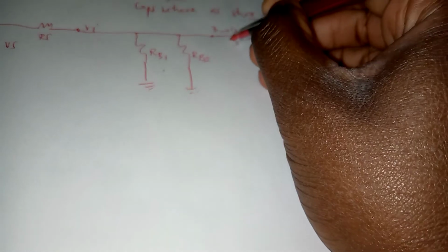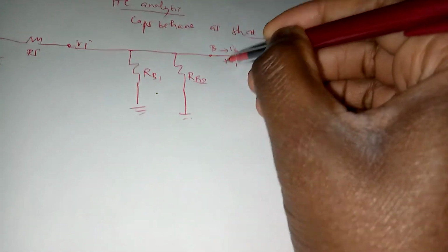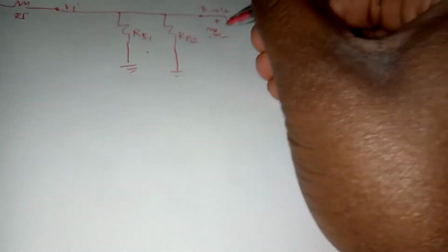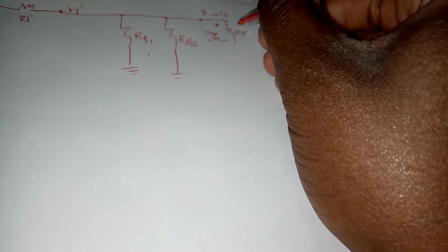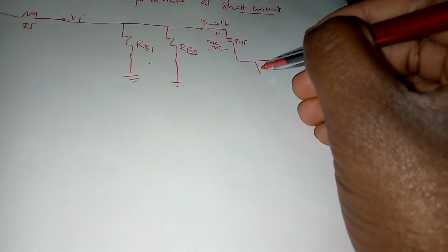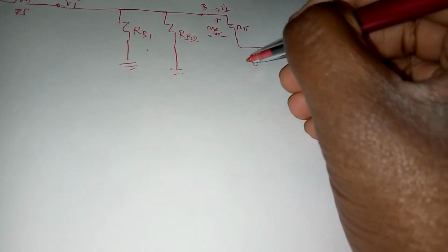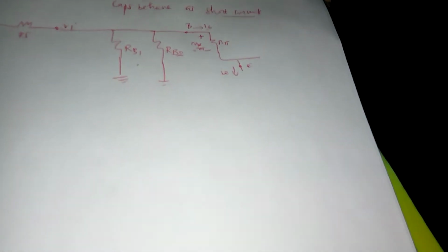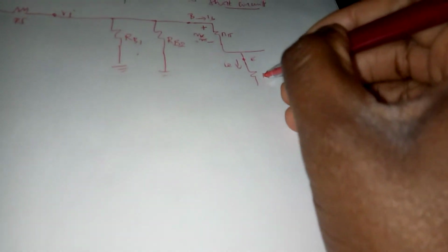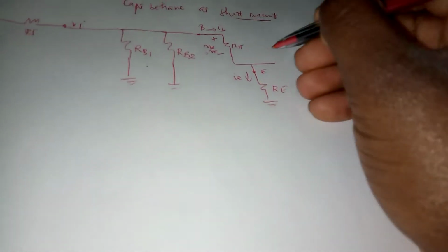We enter the transistor through its base, IB is flowing there. The small signal equivalent circuit of a transistor, it's NPN, so VB, E, V pi, it's the same thing, through R pi, across R pi, caused by IB flowing into R pi. We reach the emitter where IE flows down, and there's no capacitor at the emitter, so we've got RE present, we go to ground.